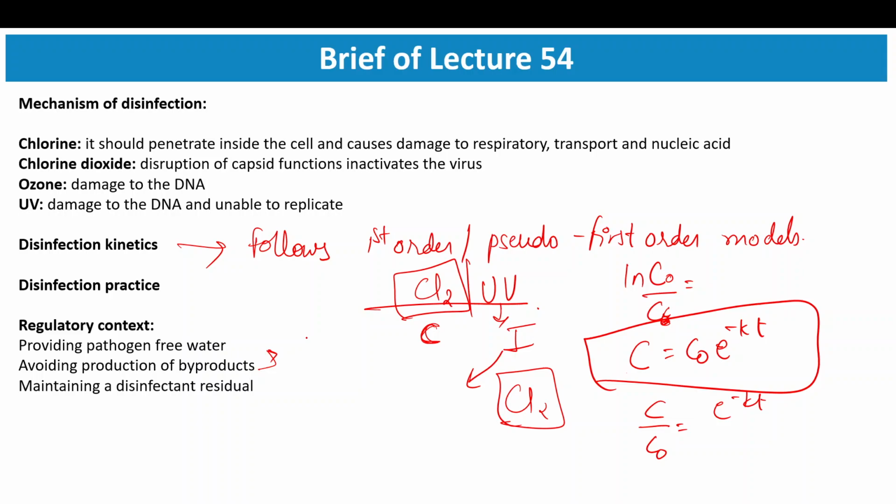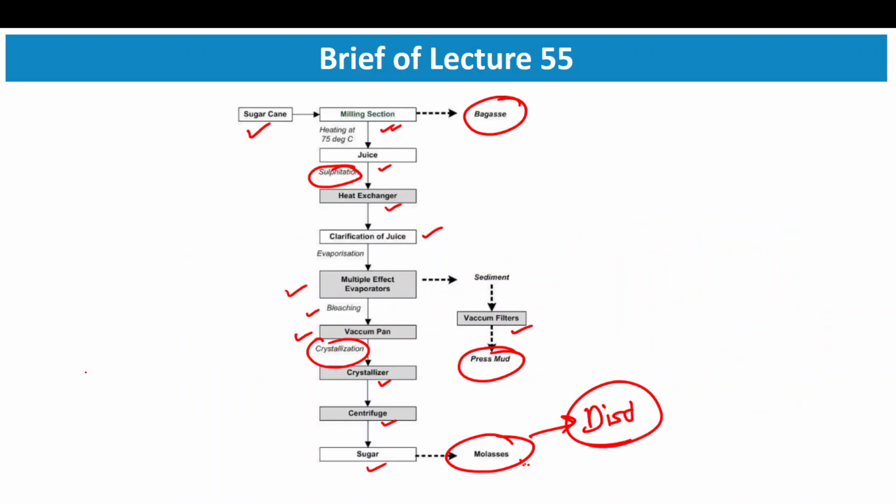So that has to be taken care of. And a certain amount of residual disinfectant level should be maintained, so that if there is any change or any plus and minus in the pathogen concentration in the feed water, it is able to take care of that.